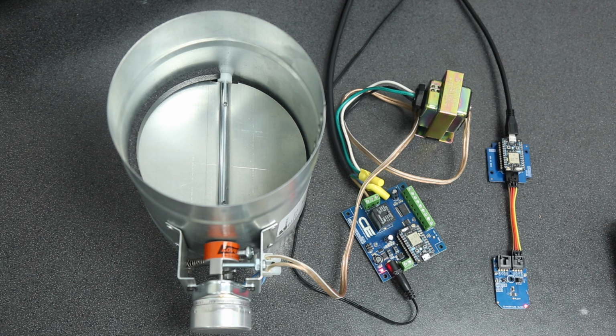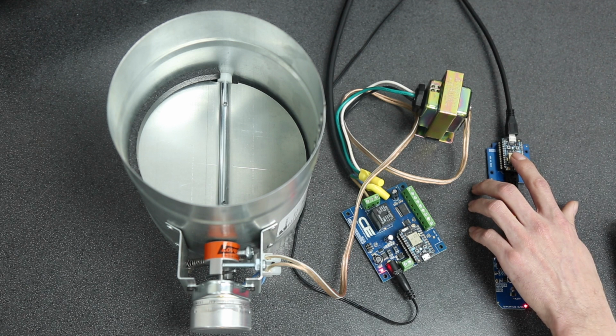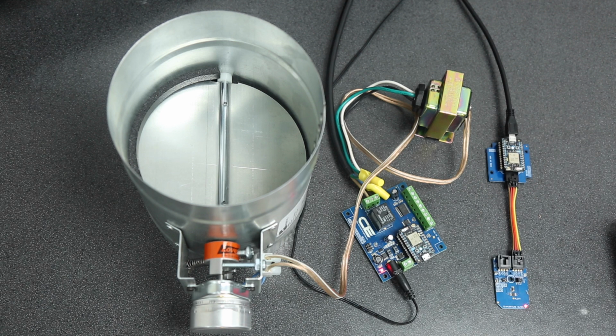So if you have your heat set at 75 degrees and the temperature drops down to 74 degrees, it's going to kick on. And you can't control what that temperature swing is. But in this firmware, we're going to be able to set that temperature swing to anything that we want. So we can say that room can get down 5 degrees below the set point before we actually open the damper. And that is fully adjustable.